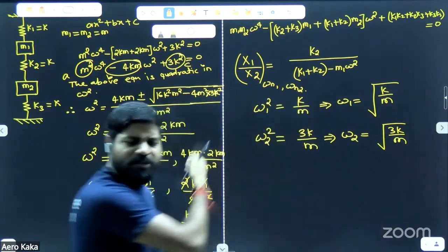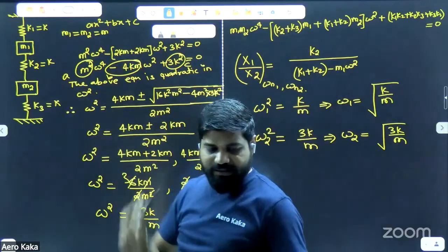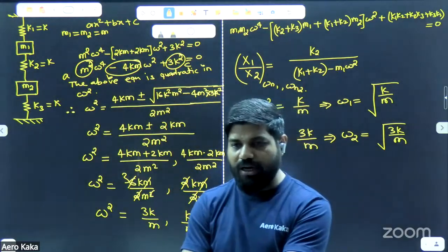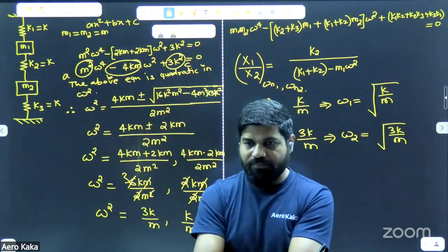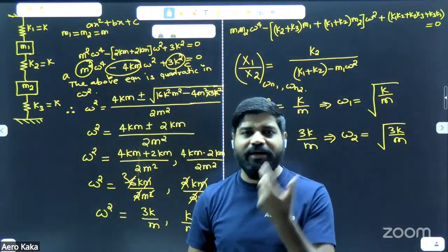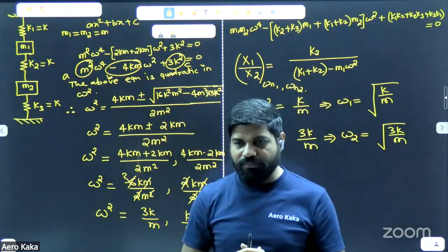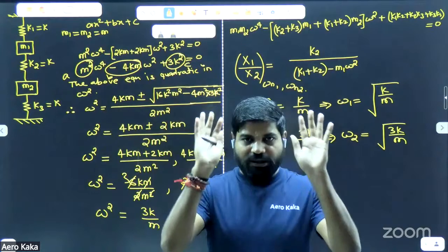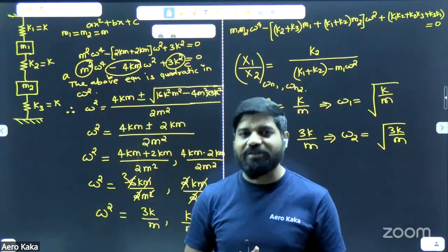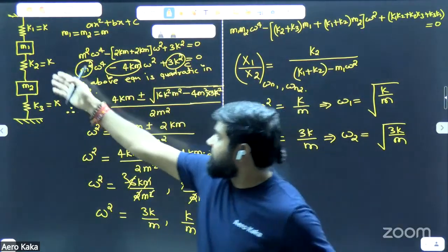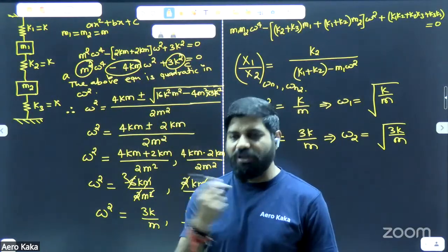Now tell me, is there any requirement of writing the equation of motion for the first mass and second mass, which is the differential equation of motion, right? Say yes or no, sir. Again, the system is a discrete system, meaning the mass is lumped, or concentrated at a certain point. It's not a distributed mass or a continuous system. Then it means that it is having finite degrees of freedom. That's the basic understanding of discrete systems, right? So with two masses in this case, this system represents a 2 degree of freedom system.